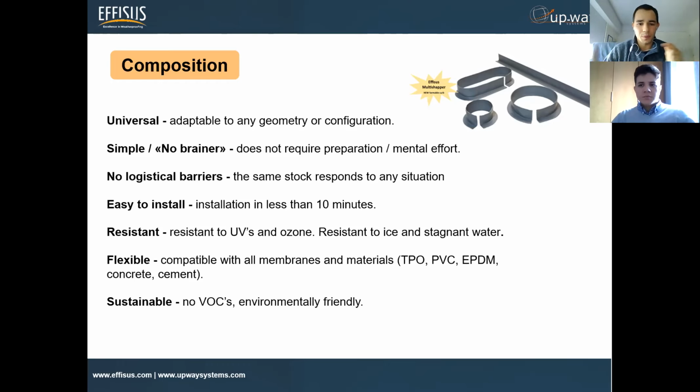We have, how can I say régua, João? In a ruler. We have a ruler. Yes. We have a ruler that you can see the perimeter, the diameter of the perforation that you have, or the pipe, and you can cut. You can use it to cut the membrane, and it will give you the perfect perimeter to put around the pipe.